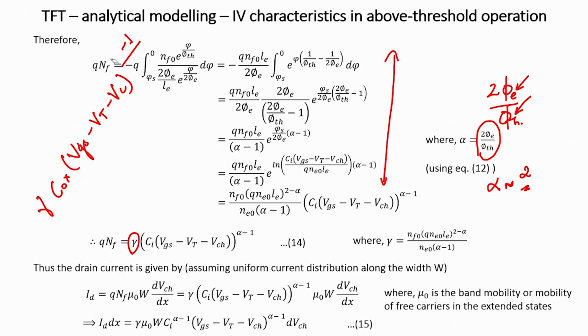So, therefore, crystalline silicon MOSFETs did not have any factor there, but this is the more general version of the semiconductor, and you find that alpha is twice Tc by T. So, that is your parameter alpha, that depends upon the characteristic temperature of the gap states.